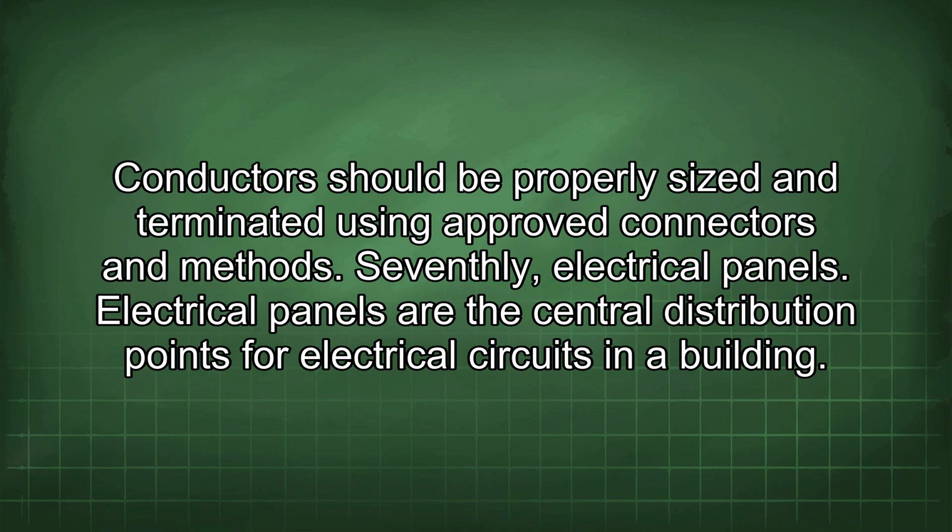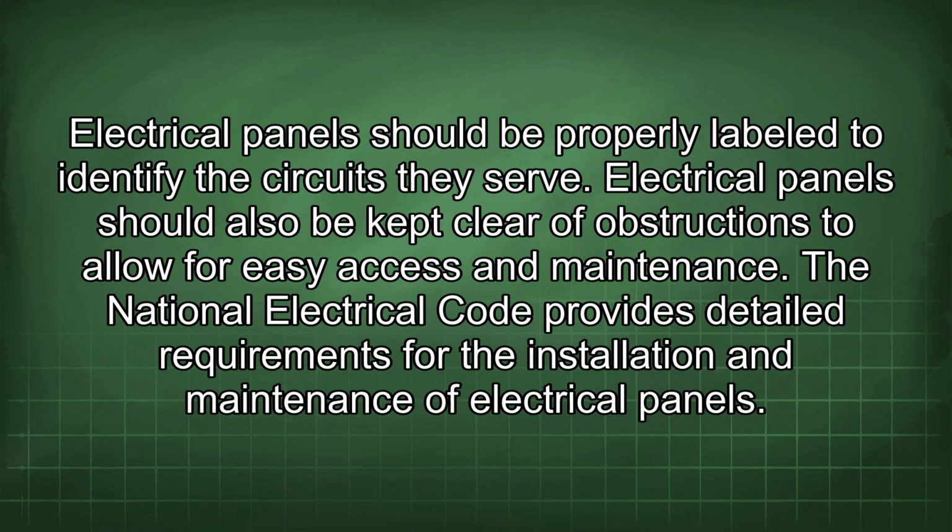Seventhly, electrical panels. Electrical panels are the central distribution points for electrical circuits in a building. Electrical panels should be properly labeled to identify the circuits they serve. Electrical panels should also be kept clear of obstructions to allow for easy access and maintenance. The National Electrical Code provides detailed requirements for the installation and maintenance of electrical panels.